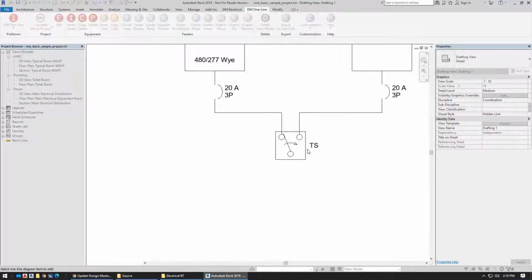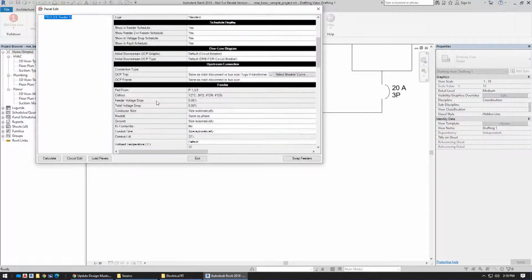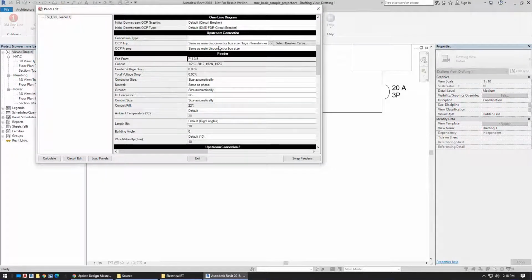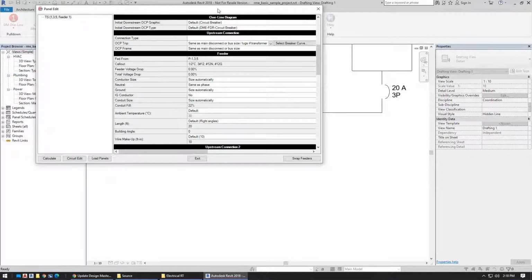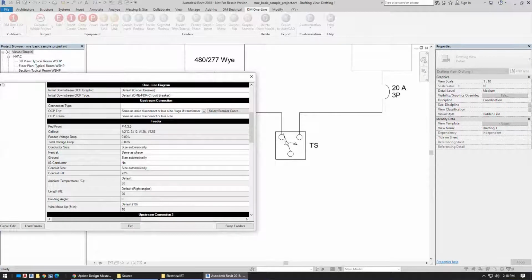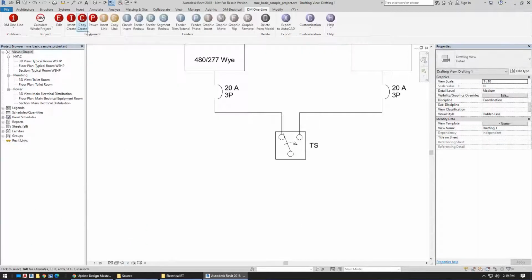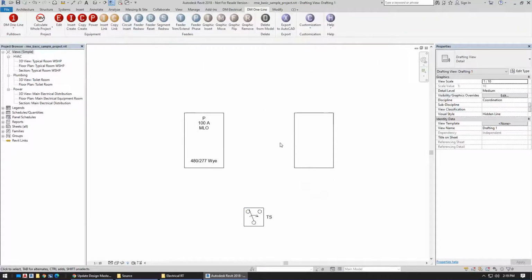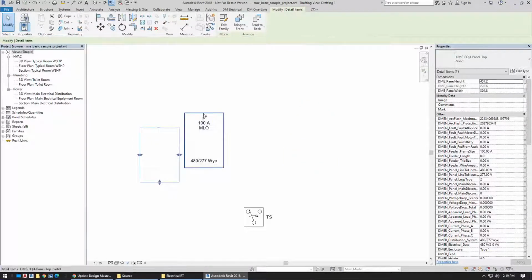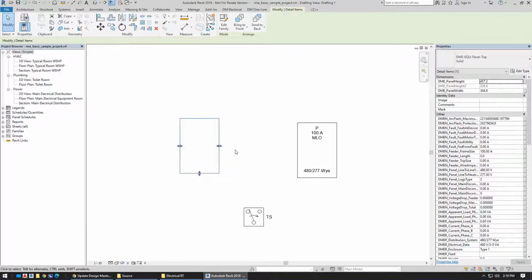If we go and edit this transfer switch, we have the first feeder and the first upstream connection, and then the second one. And the first one is drawn so that it's intended to be like the normal situation, so the switch is currently connected to that one. So this will be your first, and this will be your second. So if we try to figure out how to best demonstrate some of what you can do, now if we add a generator or whatever on the backside of that, just for the third purpose, we'll see how that goes.